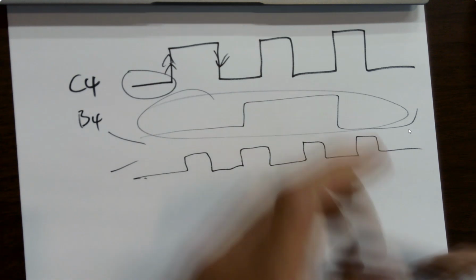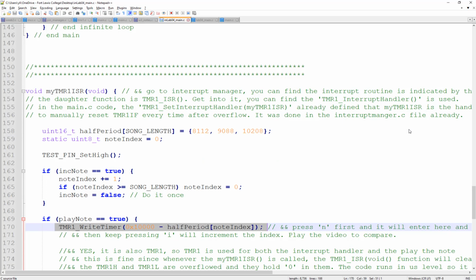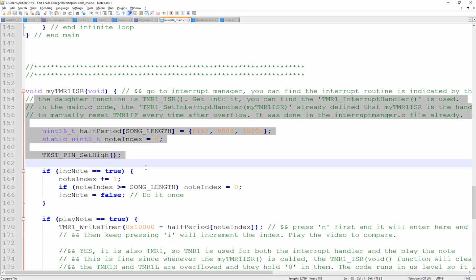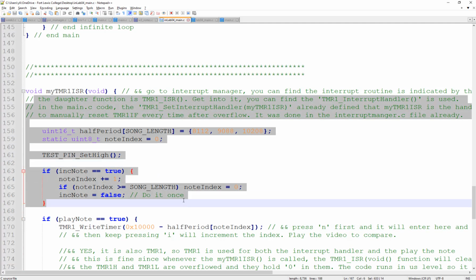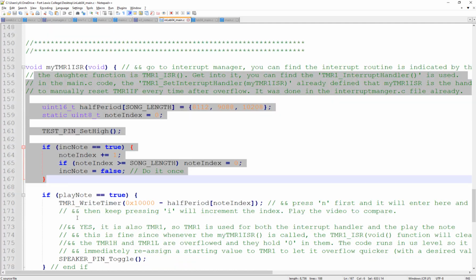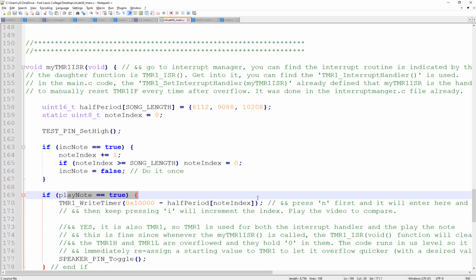All right. Now let's come back to this interrupt routine. This one, 4.1 milliseconds, gets into the interrupt routine. The way it can generate different sounds is, I told you, the top of the code will run really quickly, so you can ignore it. After it gets into here, it writes a new value to the timer, which you're talking about.